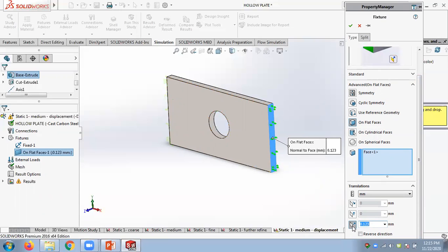Okay, so this is another way. I have a criteria. This side should be fixed. This side I have to have a maximum displacement of 0.123. So when I apply 0.123 displacement, what are the stresses? What are the reaction forces generated in this model? So you can model that way also. I don't need to give forces always. We can give displacement as the inputs.